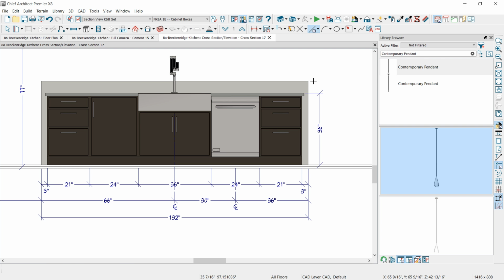I'm just going to draw a small CAD line in here, click on the dimension, place that. Again, I was off slightly, so I'll select the line, choose the dimension, put in our 6 inches, and then I'll just pull that dimension out so that it's offset. And then use the extension line and pull that in to the desired length.